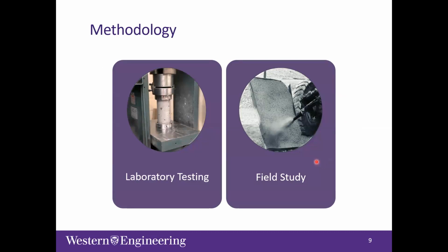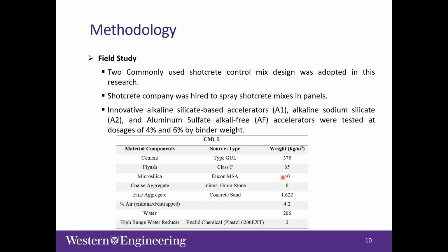First, we started with the preparatory testing, and after having the right mixes and making sure that we get the target compressive strength, we did a field study by shooting these tested mixes in the field, to simulate what we have in the field, like the tunneling project and so on. Here, I will just discuss the field study to stay within the 12 minutes.